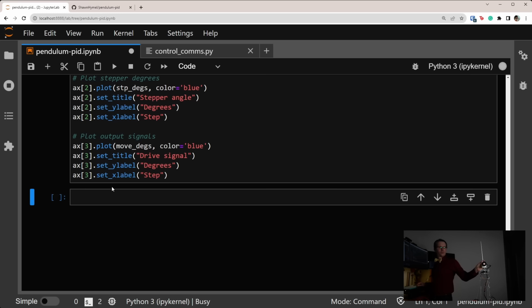First, we'll set the integral and derivative constants to 0 and guess at some value for the proportional constant. With a Kp too low, we won't get anywhere near our set point. We then adjust it so that our output gets close to the set point with maybe some oscillations. From there, we tune Ki so that we oscillate around the set point without causing the system to become unstable.